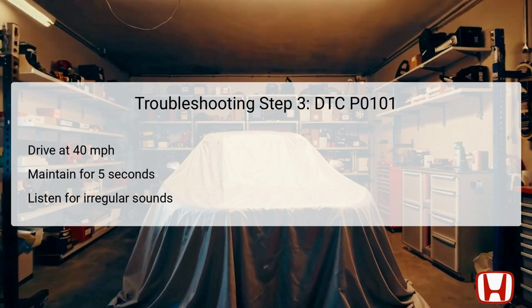While driving, listening for any irregular sounds that could indicate mechanical issues or unusual airflow disturbances can be beneficial. This step allows for observations of how the vehicle and engine are responding under practical operating circumstances, which is essential for the PCM's monitoring process. The results from this step, coupled with the previously gathered data, can confirm whether the MAF and MAP sensors are operating correctly or if further investigation is needed to diagnose the issues.